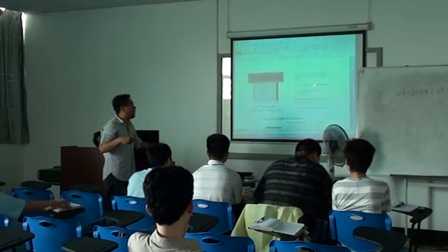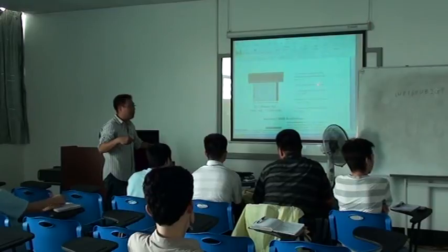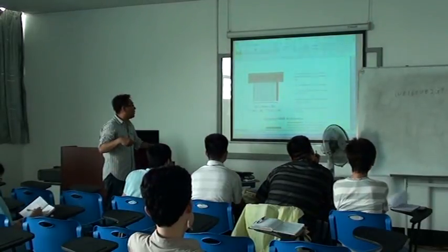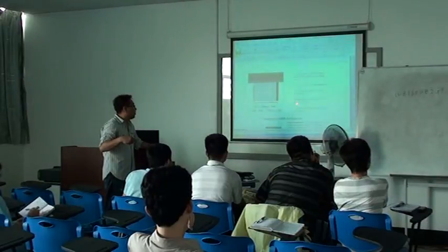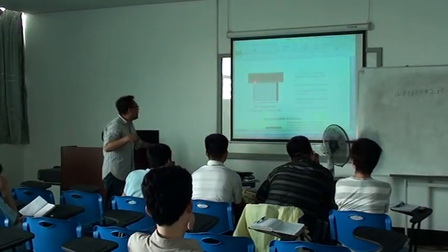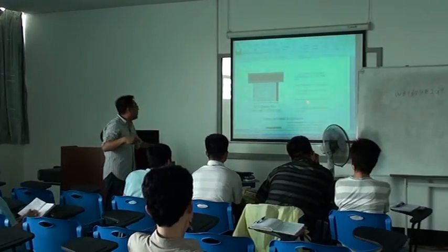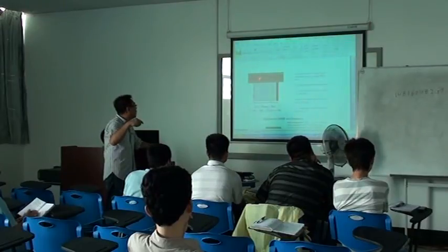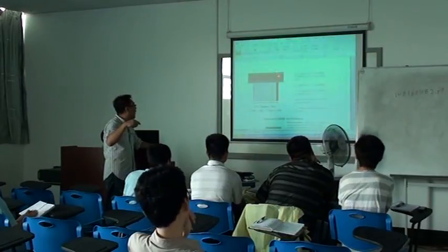But it does have 72-bit data. So normally ECC has an extra chip required to store the ECC data. So that means we have 9 chips. 1, 2, 3, 4, 5, 6, 7, 8, 9.